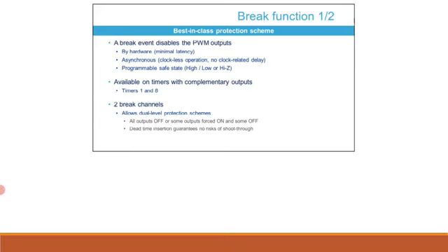Furthermore, a dead time delay can be inserted immediately before entering the fault mode for safely disabling the power stage. This prevents potential shoot through conditions. Let's consider, for instance, that the fault occurs when the high side PWM is on, while the safe state is programmed to have the high side switched off and the low side switched on.